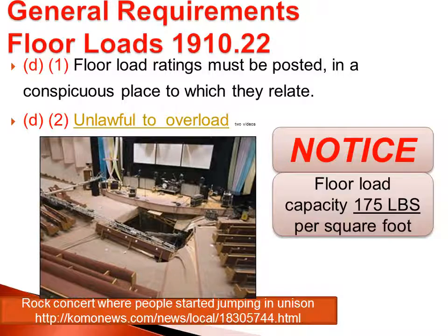So a lot of times you'll see this in the workplace where you have mezzanines, places where equipment or materials are stored on an upper deck, and there should be a sign there which clearly lists how many pounds per square foot can be placed in that area to be sure that the floor is not overloaded.